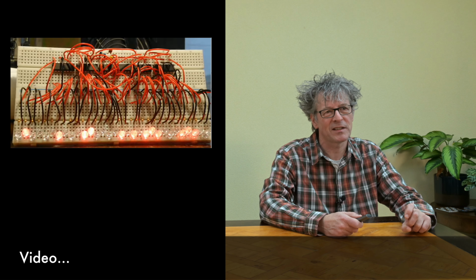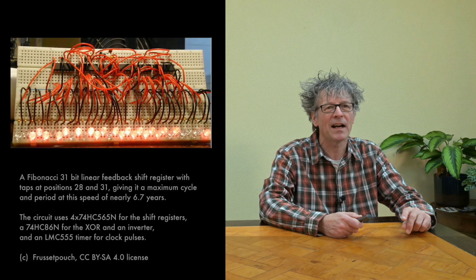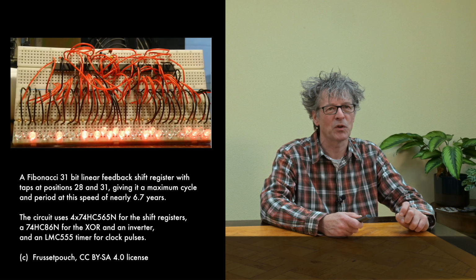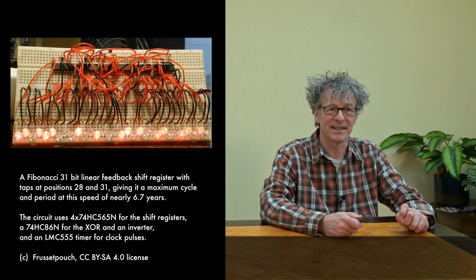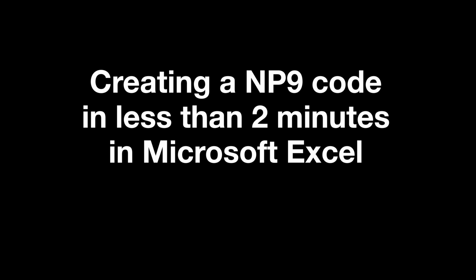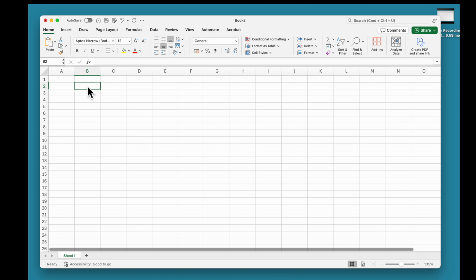Here you see a picture which is available on Wikipedia, and as you can see, people just use some simple shift registers in logic chips, and they can make even a fairly long 31-bit code that way. So it's fantastic. I could build it myself, but I don't have the time right now to do that. But it shouldn't be much of an issue, really. The actual implementation of the shift register is so simple that we should be able to do it in software itself, and pretty fast. I'll give us 2 minutes tops and we'll make an implementation together.